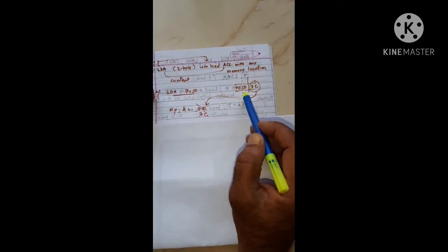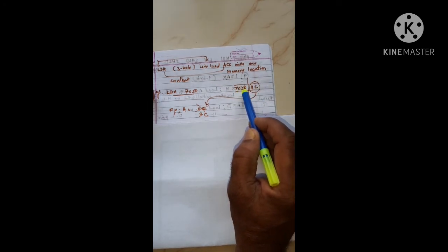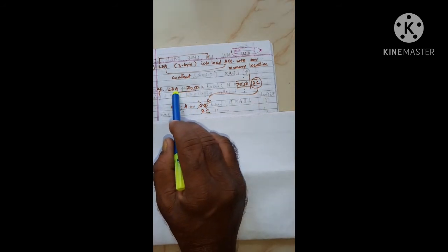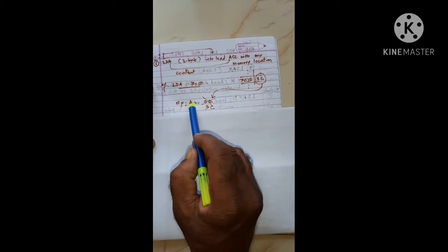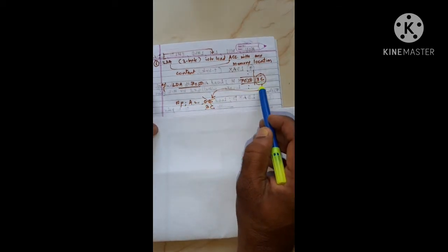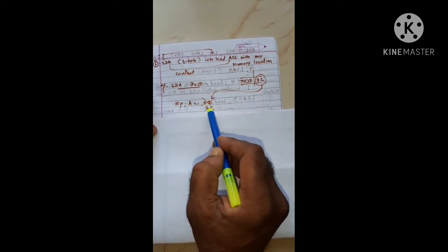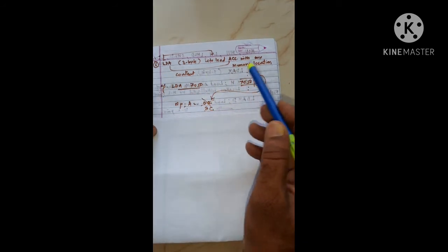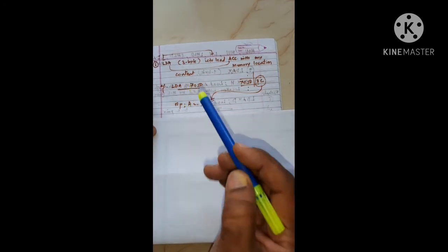If 7050 is the memory location where the content is 3C, then after the instruction execution LDA 7050, if the previous content of A is 02, it will be replaced by this memory content, and the output in the accumulator is 3C instead of 02. So this is the instruction LDA to load any memory location content directly into the accumulator.